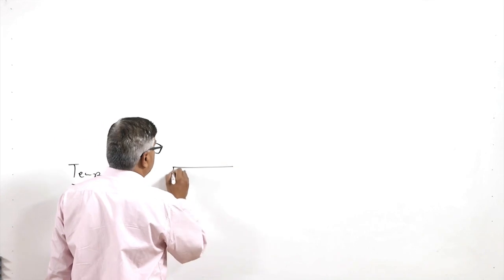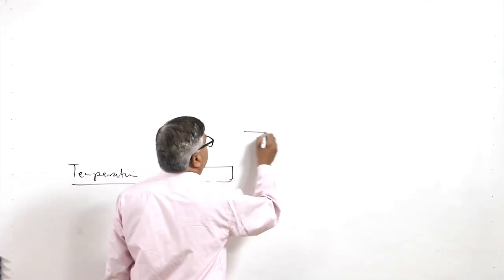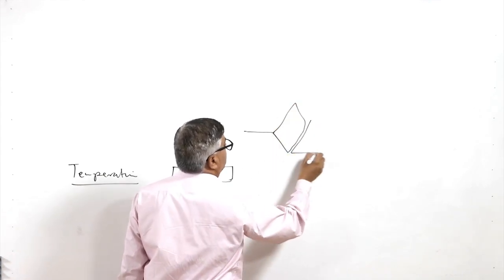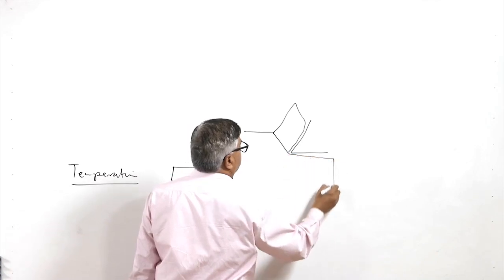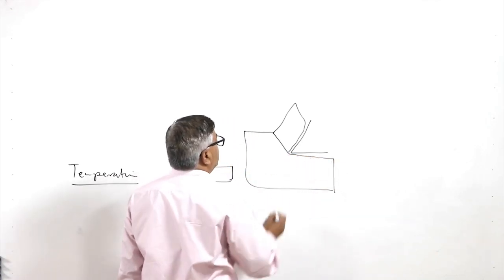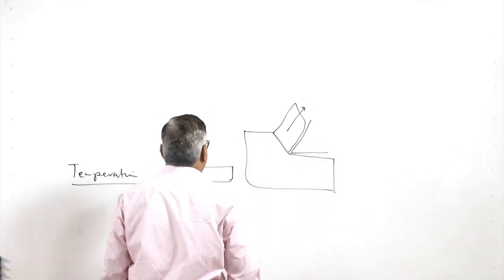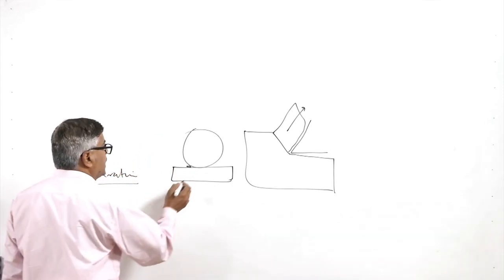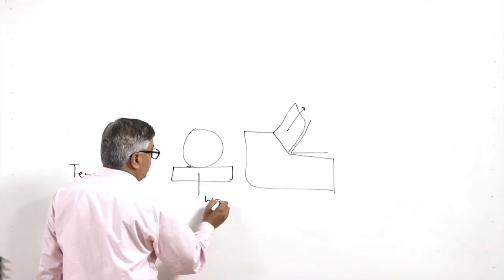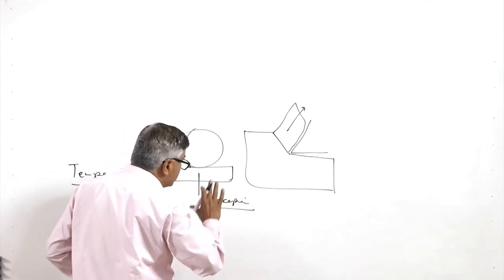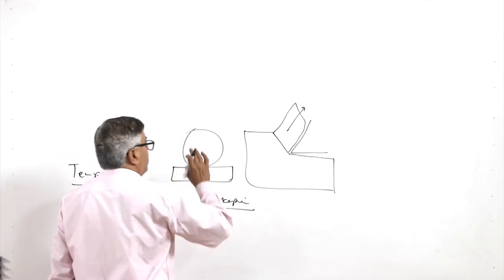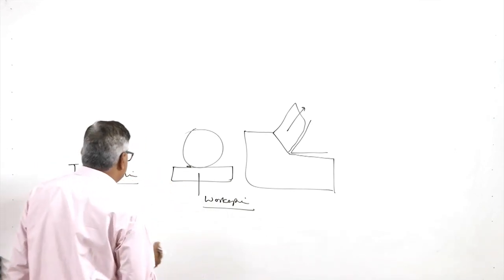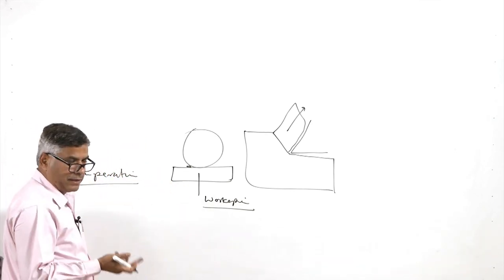If we compare the scenario with conventional machining, in conventional machining the chips carry away a lot of the heat generated in the primary shear deformation zone and the secondary shear deformation zone. So the chips carry most of the heat, while in grinding the chip size is very small and the chips are very fragmented. So the heat generated is mostly carried by the workpiece. Since most of the heat is retained by the workpiece, and part of it is also retained by the wheel, the workpiece is very badly affected by the heat generated during the grinding.